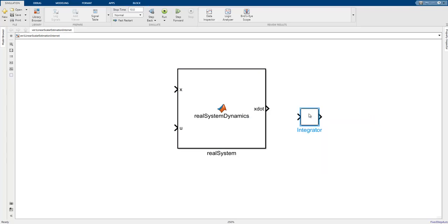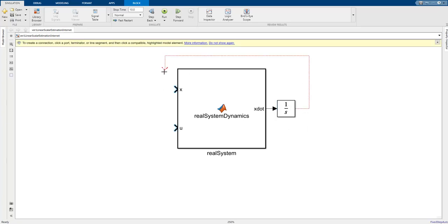Okay, real system dynamics. If I have this kind of dynamics here, I need to push the integrator to solve this x dot equation. This integrator produces the x value, and so I can feed this x value to the input named x. So x dot in time creates the x, and the solver of our dynamics is iterated. Okay, this is how Simulink works.